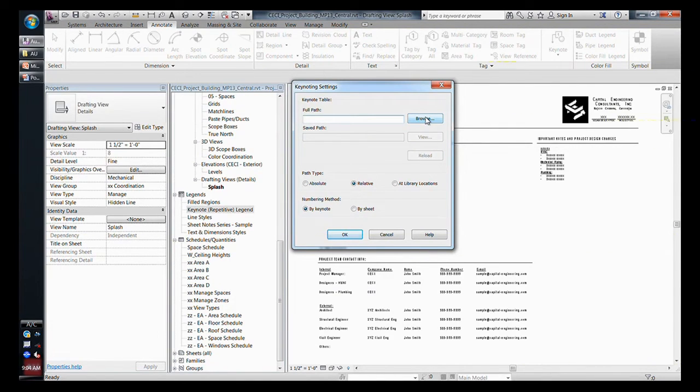Our MEP notes tend to be rather specific to the situation and not so much like the architectural. They can just say this is a 3/4 of an inch gypsum and just standard notes, right? I'm not saying we don't have standard notes. We do. And that's why I'm saying you shouldn't start with a blank text file. You can start with a text file that contains some standard notes they can pick from, and they can continue developing that text file further from there.